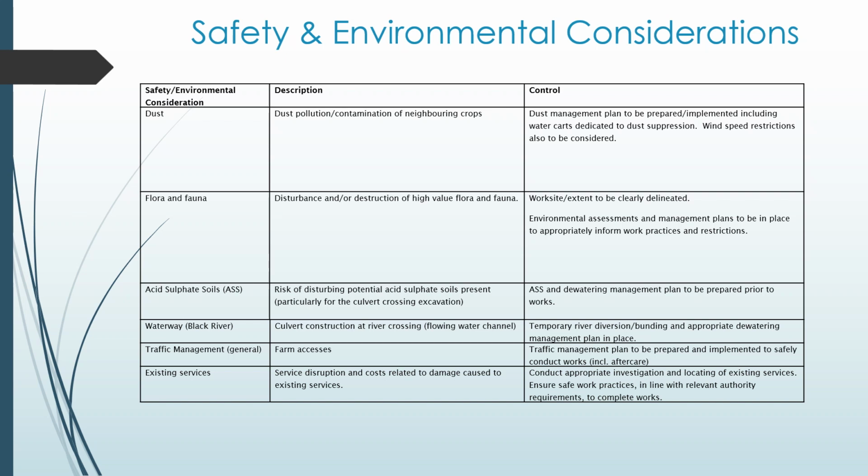The waterway itself at the culvert, there might be the need for a temporary river diversion or bunding and appropriately dewatering. So again, having a dewatering management plan in place. Traffic management in general, which we've discussed, but obviously a high safety concern.